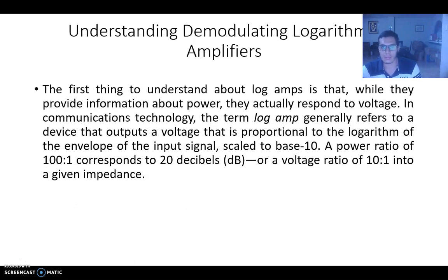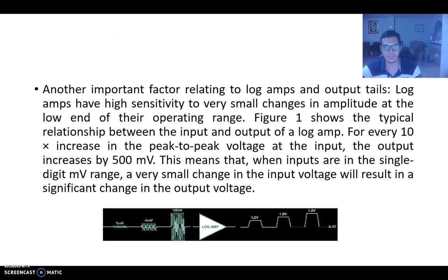Understanding demodulating logarithmic amplifiers. The first thing to understand about log amps is that while they provide information about power, they actually respond to voltage. In communications technology, the term log amp generally refers to a device that outputs a voltage that is proportional to the logarithm of the envelope of the input signal, scaled to base 10.